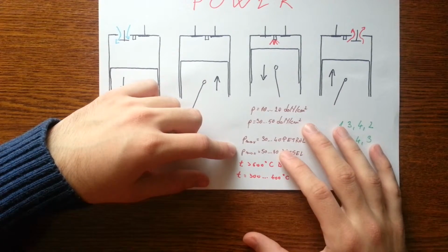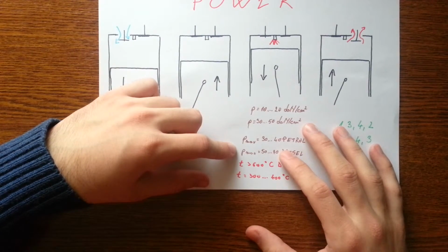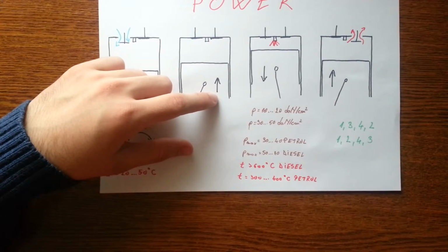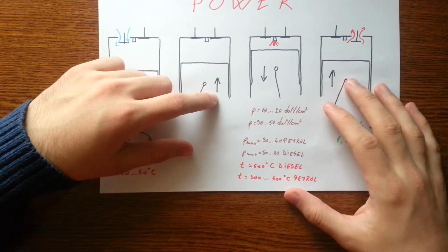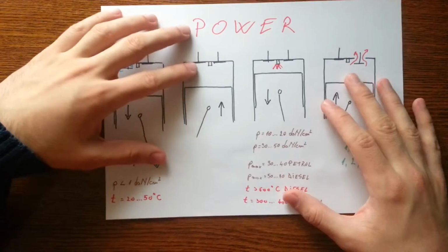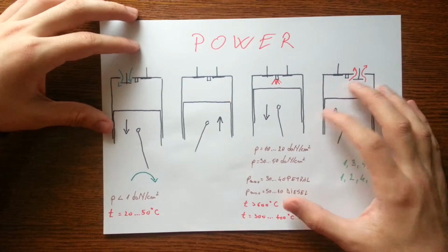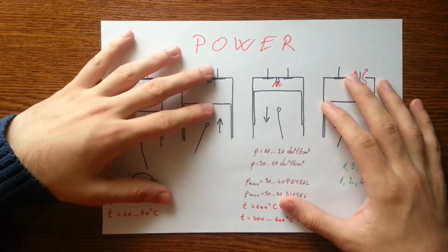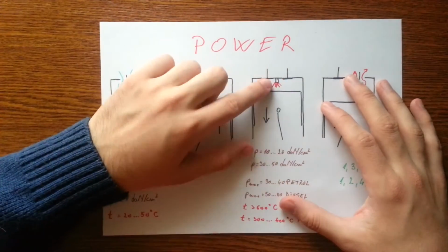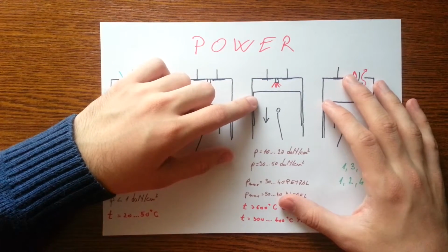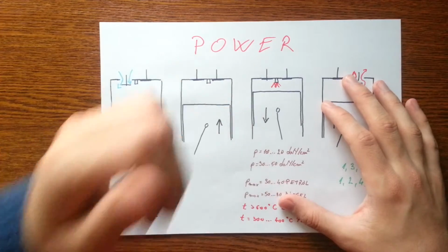Firing order is also important. We know that the firing order is the sequence in which the spark plugs ignite the mixture in each of the engine cylinders. This is controlled by the distributor, which directs the flow of the current to each plug at the correct time during the engine's 4-stroke cycle.